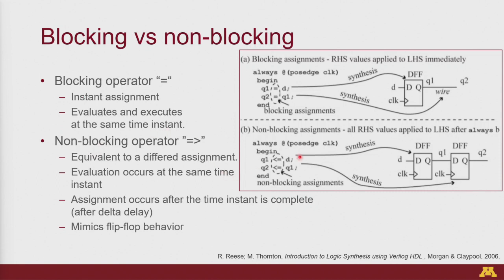Now the other thing you need to keep in mind, which is still a separate thing, is blocking versus non-blocking operators. There are basically two ways you can do assignment in Verilog: either blocking operators or non-blocking operators. As the name suggests, blocking means that until it completes the assignment, it will block the execution of this device.